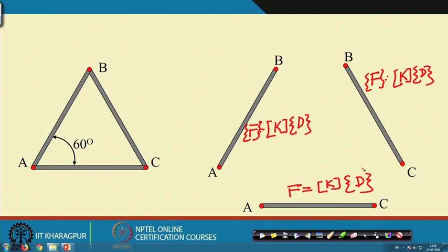But now, since we have to divide the entire problem into small pieces, we have to write this equation for every piece, and once we have written these, we will assemble all these equations. We get a set of equations for this member, and a set of equations for that member, and then we combine all these sets of equations to get the equations for the entire structure, and then we solve it, right?